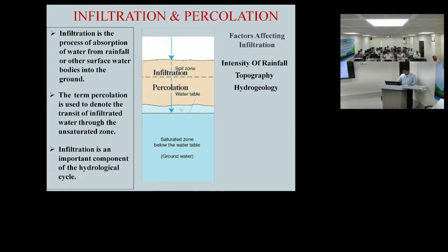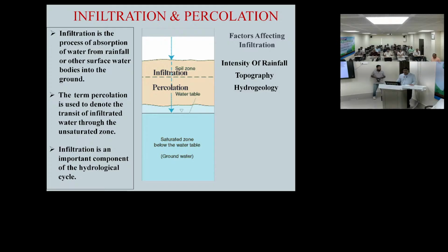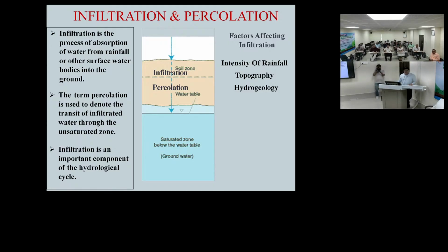Means if any groundwater, if any soil surface is to be recharged, there ultimately there is a sedimentation. Sedimentation means there will be sand particles. In the sand particles, ultimately we know there are porous spaces, because between two particles, sand is silica also. So the porous spaces have to be filled first. Once the porous spaces are not filled, it is called unsaturated. Once it's filled, it is called saturated. So percolation will transit the infiltrated water to the unsaturated zone.